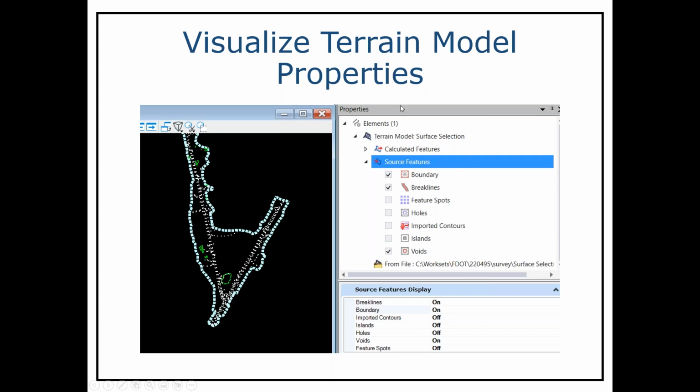but they are 3D, which brings up a situation where you may have a topo file which is 2D and you need 3D features, but you don't want to send the survey crews back out, but you do have a terrain model. The TIN that was created previously could have break lines and points in it. If it does have break lines, you can actually visualize those break lines and bring them into the file. They won't be on the right features, but you can do that too. If push comes to shove, it's probably easier than sending a crew back out to collect this stuff.